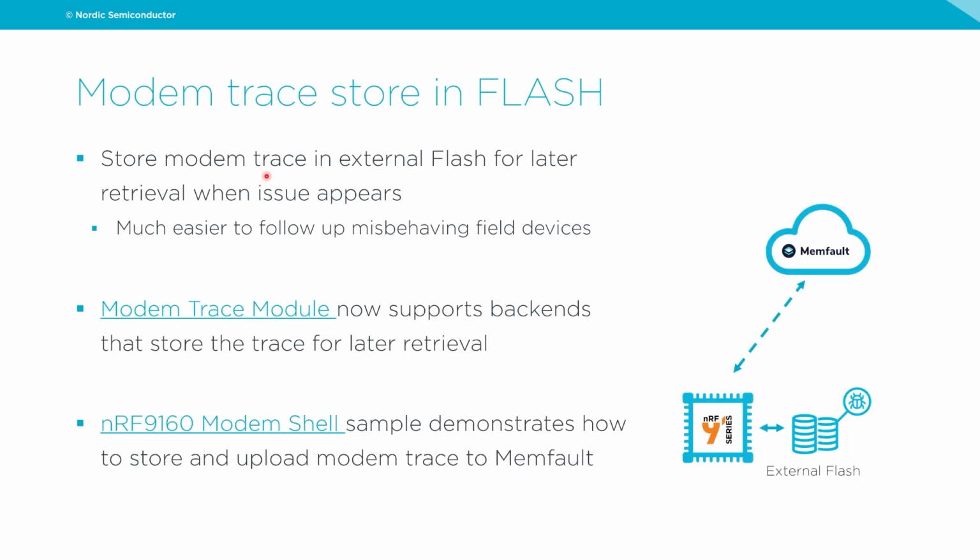We have also added support to write the modem traces to flash, so you can store the modem traces to flash so that you can later retrieve them and analyze them if you happen to have an issue. This is especially useful in the field, so you can analyze if there's some kind of misbehavior on field devices. Prior to this, there was support for UART and RTT backends. So now you have the external flash backend as an additional option.